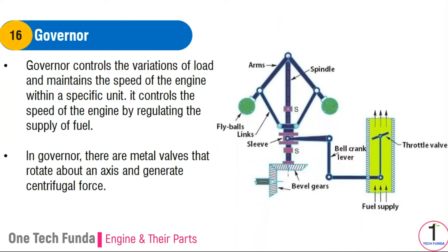When the load on the engine suddenly increases, the engine speed will decrease. A greater decrement in engine speed can stop the engine. The governor is connected to the engine crankshaft, and when the speed of the engine decreases, the governor also slows down and the sleeve moves downward, opening the valve of fuel supply with the help of a lever. The increment in fuel increases the speed of the engine to mean speed. Whereas, in the second case, when the load on the engine decreases, the governor also decreases the fuel and controls the speed.